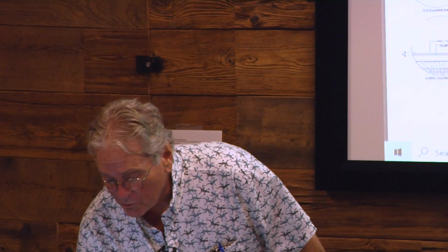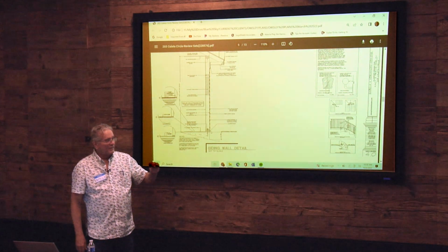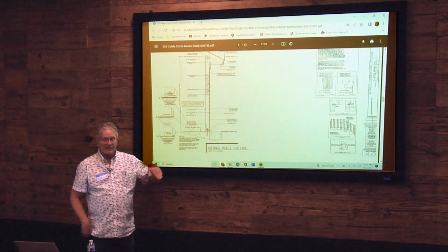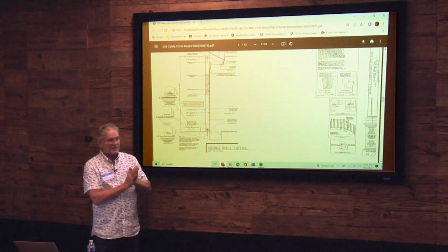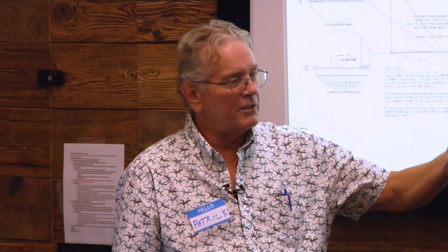Where it came up for me is when my MTO guy, again, he called, and you see this little detail down here at the very bottom where it shows 2 plates bolted to the foundation. There are many instances where you would put 2 plates in brand new construction. And I can get into many details about that, but let me just tell you, that's not a typical detail. So again, it is a typical wall section, but it's not applicable to this house. Because the MTO guy called me up and said, are you going to double plate the base plate? And I said, why do you ask that? And he said, well, it's shown on a detail. So I looked at the detail and I said, no, they never talked about doing that.